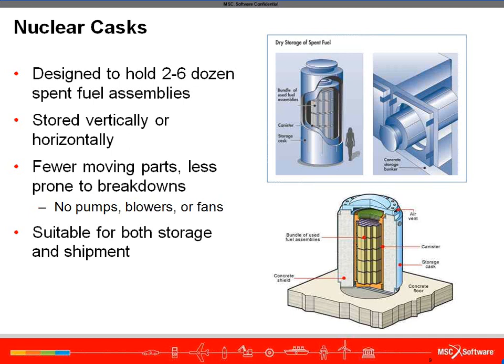In use, they can be stored vertically or horizontally, and you see some images of that in this slide as well. In some cases, there will be an inner cask that's stored inside a concrete vault that then acts as the moderator. So the elegance of these casks, at least on the surface, lies in their simplicity. No moving parts, no water to pump, no active cooling requirements. Even better, proper design allows the cask to not only act as a storage container, but as the requirement arises, to act as a transportation container as well. Of course, as you can imagine, this introduces a whole new set of design requirements.